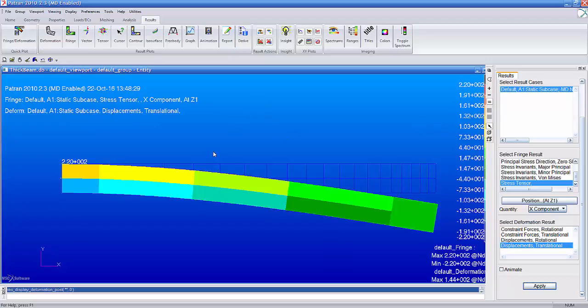So when we look at the stress distribution like this, we see that there's no way to see a linear distribution through the height of the beam as we expect for the bending stress, because we only use 2 elements. So let's go to a finer mesh and see what happens. And we see the maximum displacement came out to be 144 millimeters, which is here.